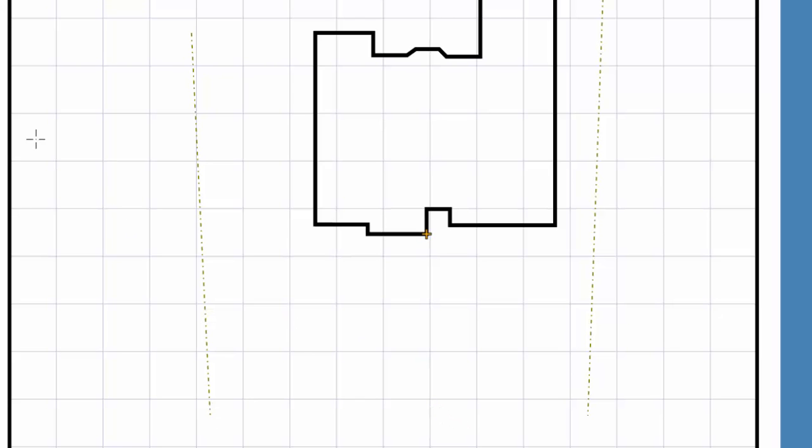I start the line command, drag the cursor near the front porch of the house and press the right mouse button to snap onto the front of the house. I press the down arrow key and enter 30 feet in the distance box. I press enter to end the command and enter again to end the line segment.